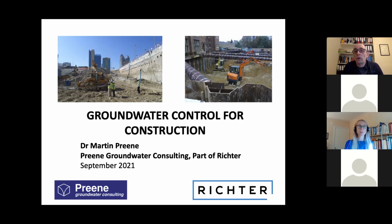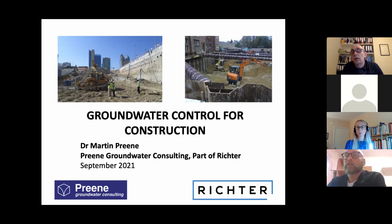And it's even more difficult when you are comparing a pumping system with an exclusion system, because if you're being very efficient, you could use your exclusion system, your walls, to be part of the structure. A diaphragm wall, for example, is very expensive, and to put in a diaphragm wall is almost certainly going to be more than a temporary works pumping system. But if the diaphragm wall is part of your structure, that can be a very cost-effective way, because you are using it twice. You're having it as a temporary barrier and your permanent barrier. And the only way you can compare that is to look at your own project.